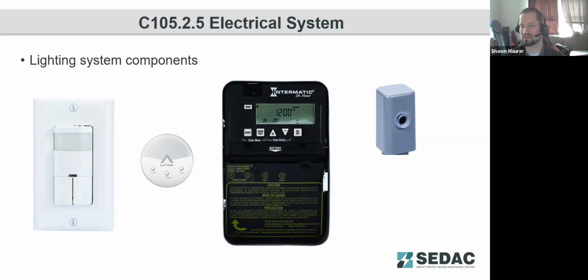If you've got a building automation system, or if they're wired up to an occupancy sensor, that the proper signals are having the proper impact on the lighting controls. For daylight sensing and outdoor controls that are hooked up to photocells, making sure that those photocells are properly located.